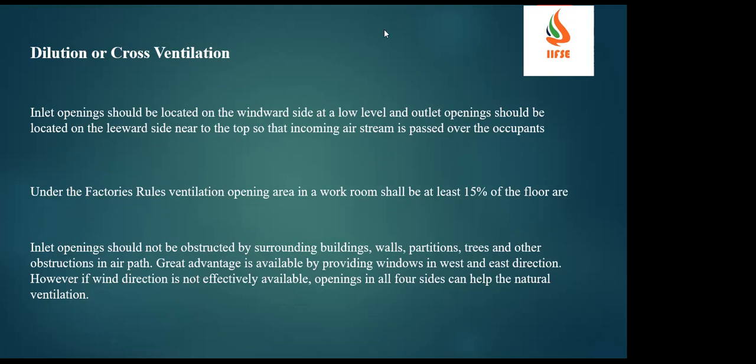What does it exactly mean? 15% of your floor area, in the sense, for example, if this is your complete shop floor, it is 100 SFT. Out of this, 15 SFT you will keep in the form of openings, either windows or doors,